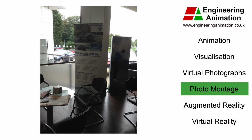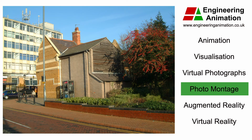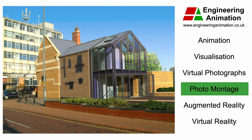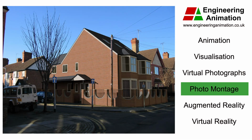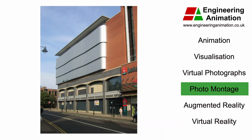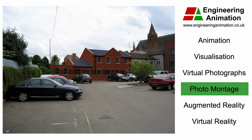Now, photo montage. So here, we've composited rendered 3D models onto background photos of the site to show the proposal in context, or in situ. Where we put a virtual building onto a real location, we match the physical camera location, the lens length, and the camera settings in the 3D model. We also match the precise location of the sun using the time, the date, and GPS location data. We can also replicate the cloud cover and render so the model's shadows fit into the photo seamlessly.